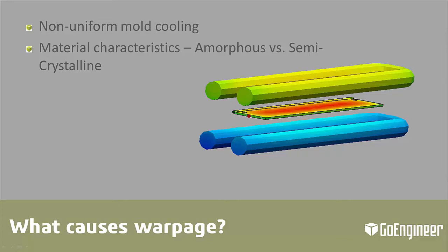We also have, in our processing of injection molded parts, the ability to control warpage or create warpage with the settings on our injection molding machine. If we have excessive packing pressure during the molding process, if the parts are overpacked, the system is trying to force too much material into the cavity, which will cause excessive molded-in stress.